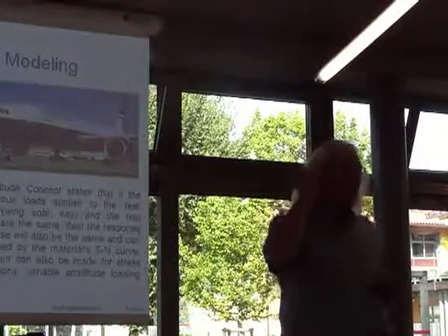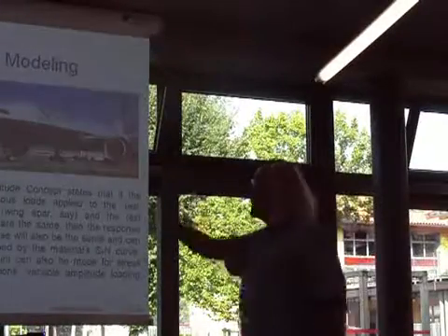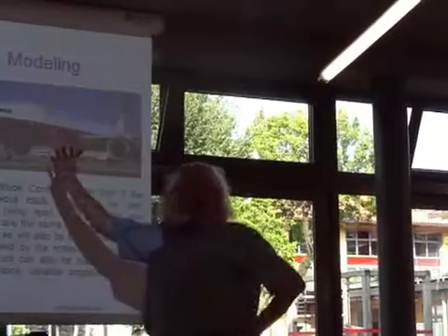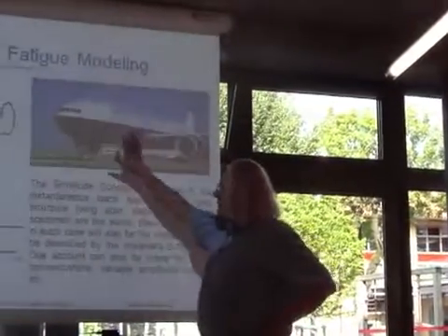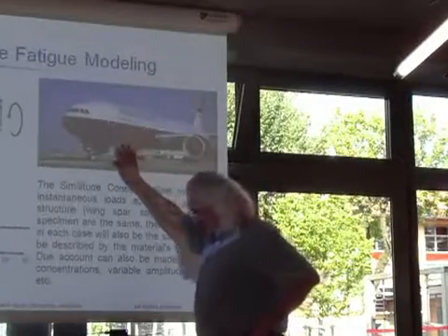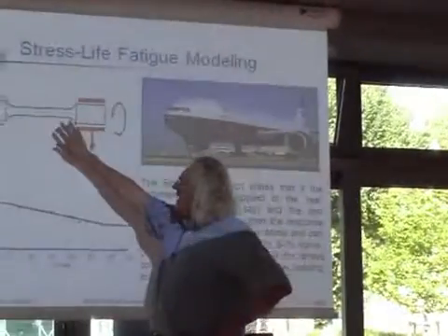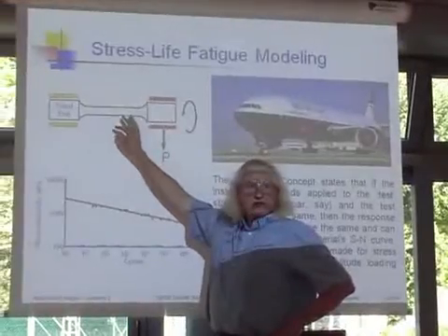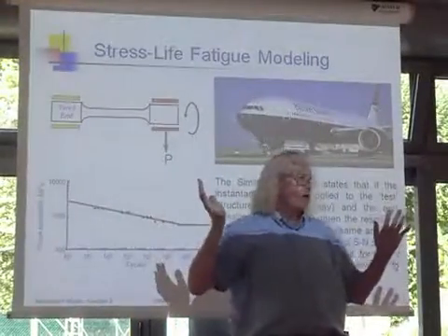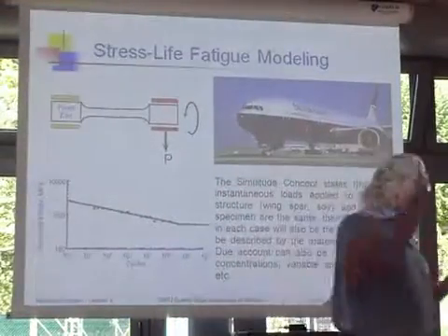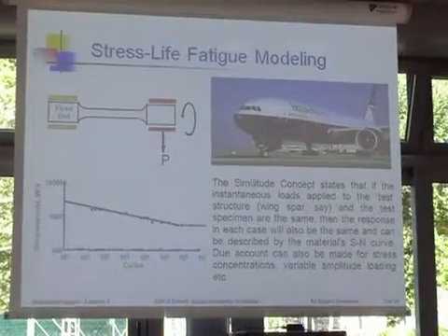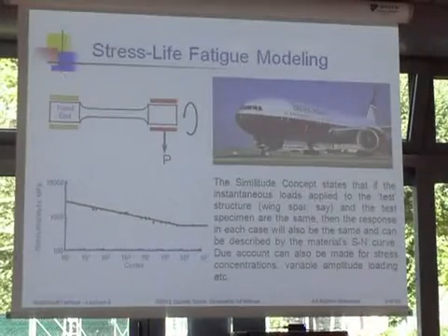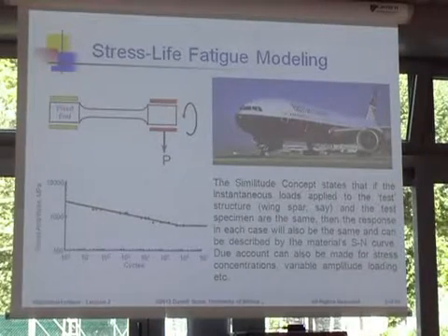So this is a good model, but it has nothing to do with the size or shape. Right? This is a good model because the physics is the same. What parts of this really big structure is the failure physics governed by the nucleation of cracks? And so this approach will work very well. Very well. And now I can go on and I can choose, oh, what is the very best stress life model to use and all that kind of stuff. Right? That's secondary, in terms of getting the big picture correct.